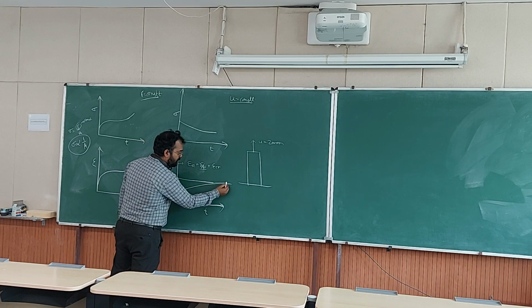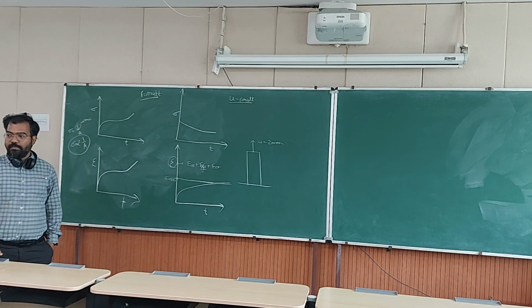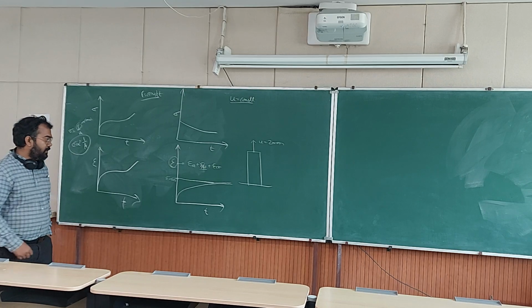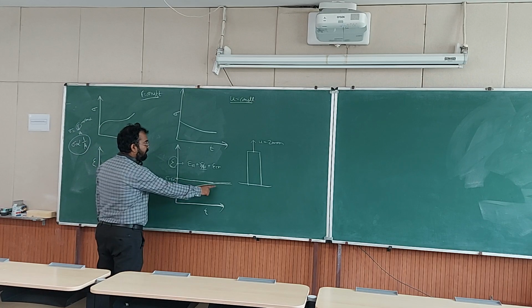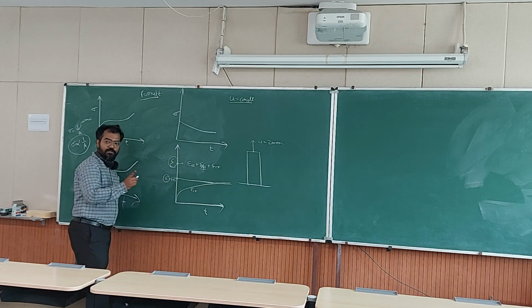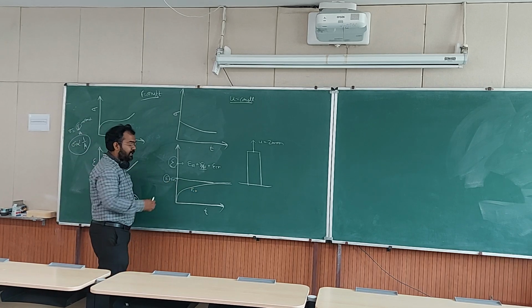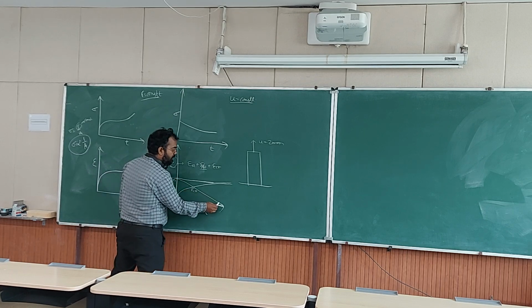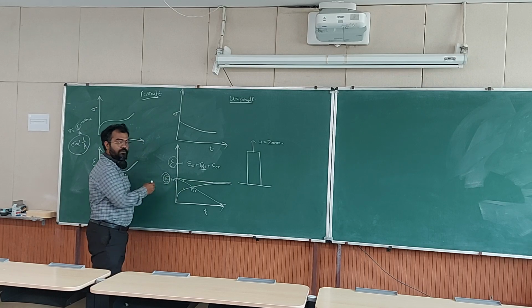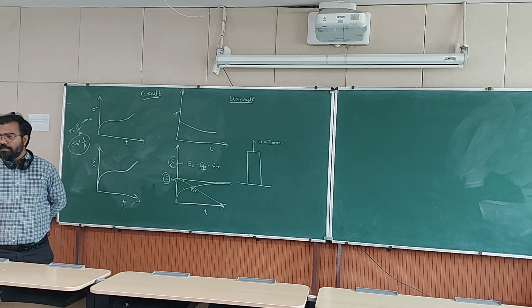And this will become asymptotic. So at a very long time, the creep strain is going to be equal to the total strain. Something will go to 0, starting from here, and that has to go to 0. And at every point, the summation of the two will be equal to this, and that will be constant. Is it making any sense to you?